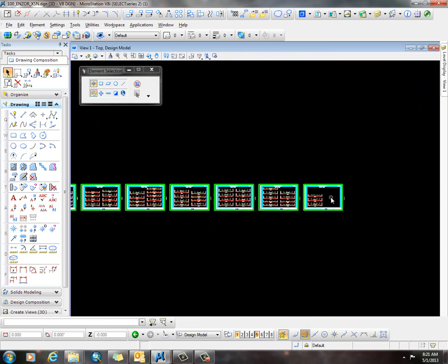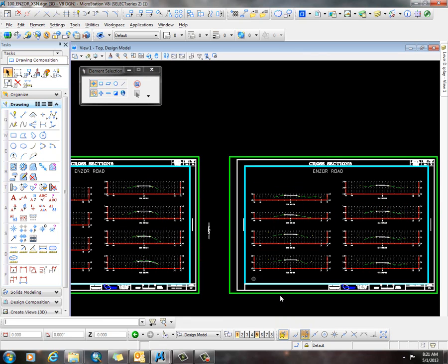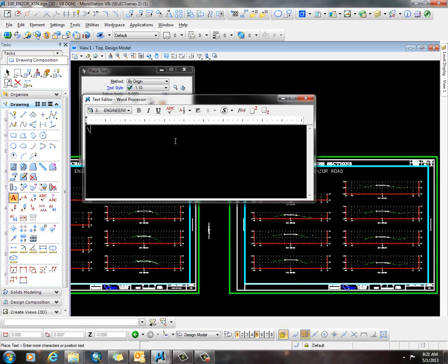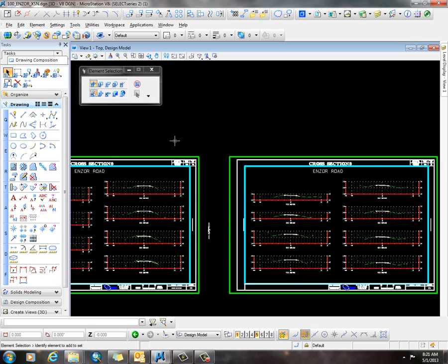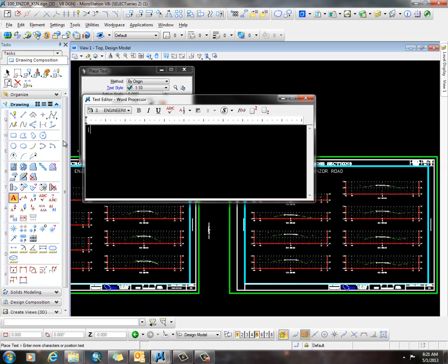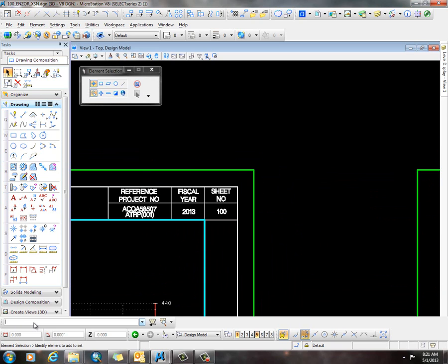Now we're going to cover utilizing the pipe command. The pipe is the key that is above your enter key on the right hand side of your keyboard. It is not the slash. It is when you hit shift and slash, it's basically a vertical line. It's called the pipe command. Now utilizing the pipe in the key-in tells MicroStation to repeat the command X number of times.